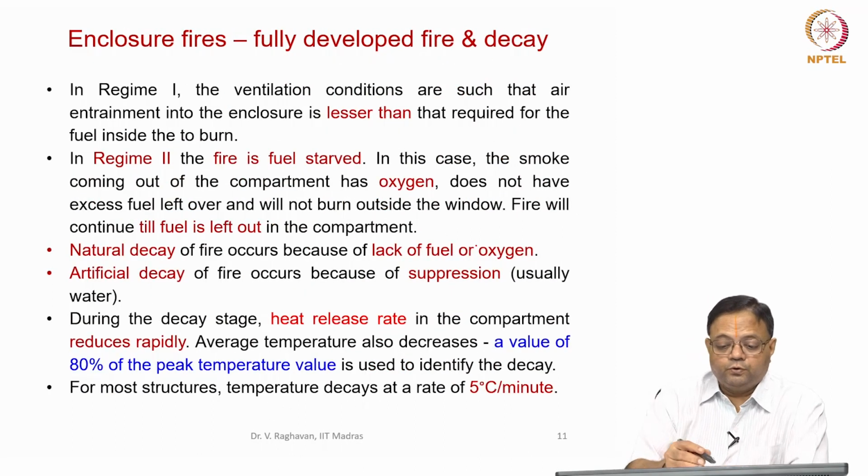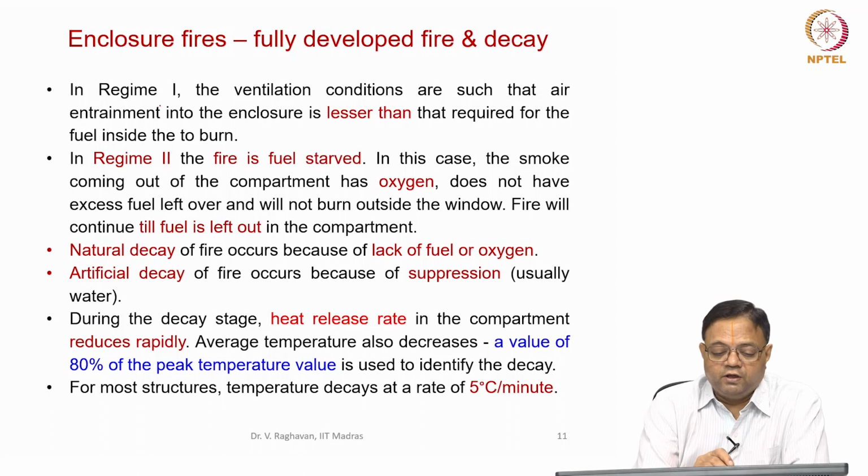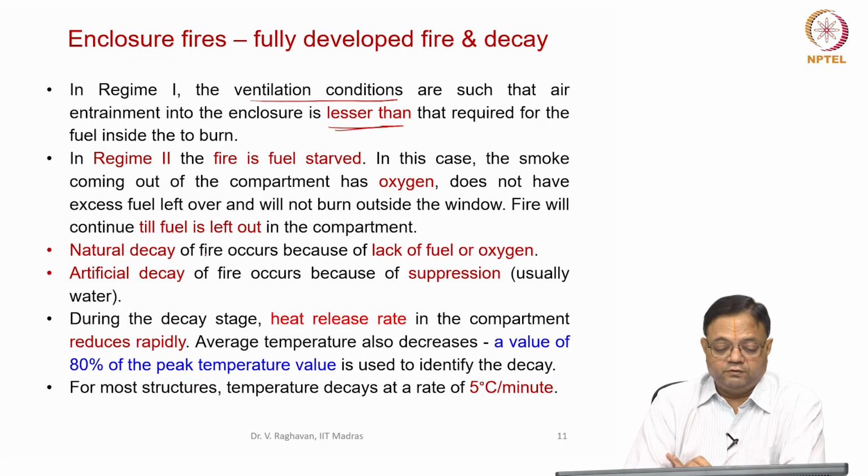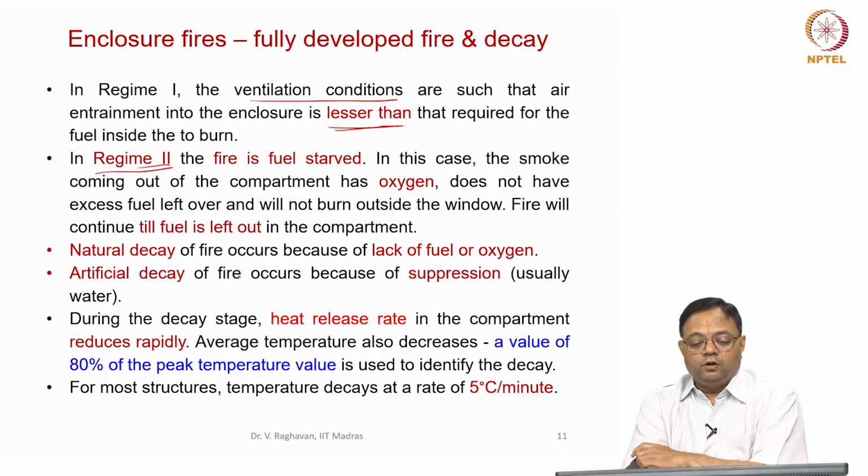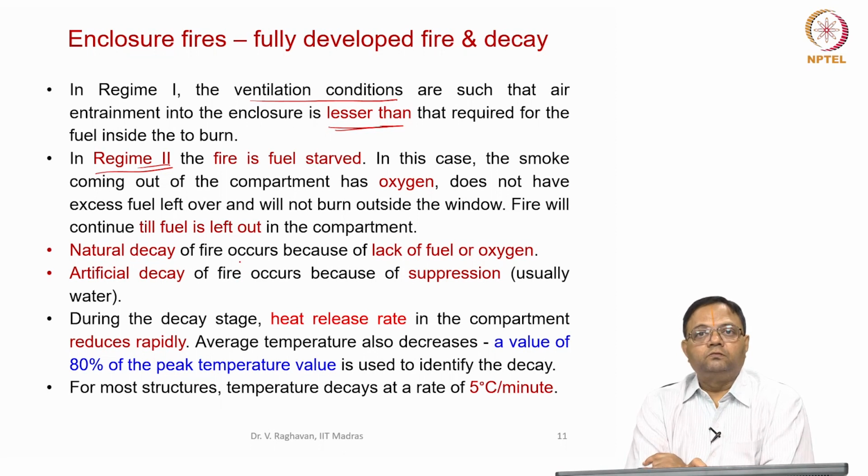Second regime. Now, in the first regime, ventilation conditions are such that the air entrainment is lesser than that required for the fuel to burn within the compartment. That is the first. The second regime is where ventilation is good, but there is not much fuel to burn.